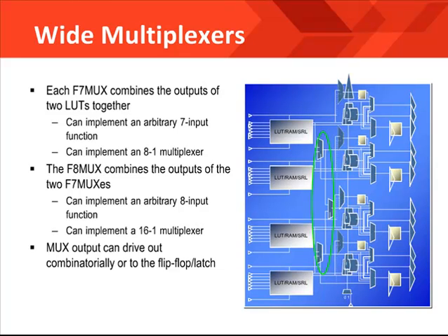These dedicated multiplexers are used to improve the speed of large multiplexers and save LUTs for other purposes. The reason that these multiplexers improve the speed of the design is because there is dedicated routing between the muxes that are low fan-out and fixed between the logic resources. It is also fast because the dedicated multiplexers are faster than building the equivalent logic just with lookup tables.